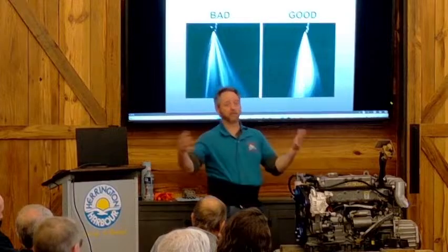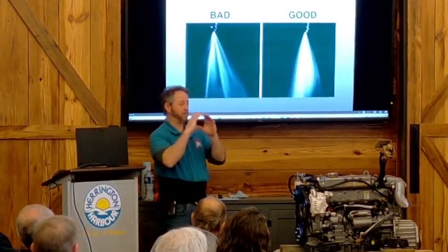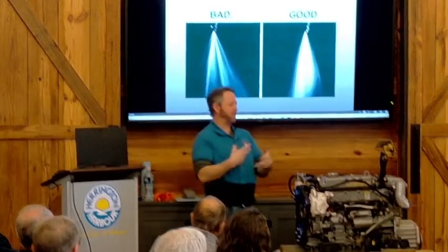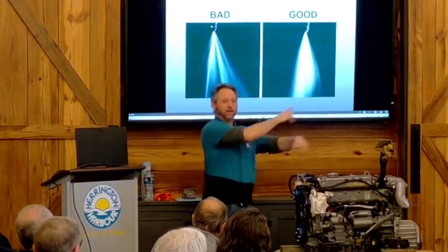So when you start getting to the larger engines, which have larger capacities, the pipes and heat exchangers and everything, there's more mixing happening. So you've got to start off at a stronger mixture because it gets diluted on its way through the whole system.